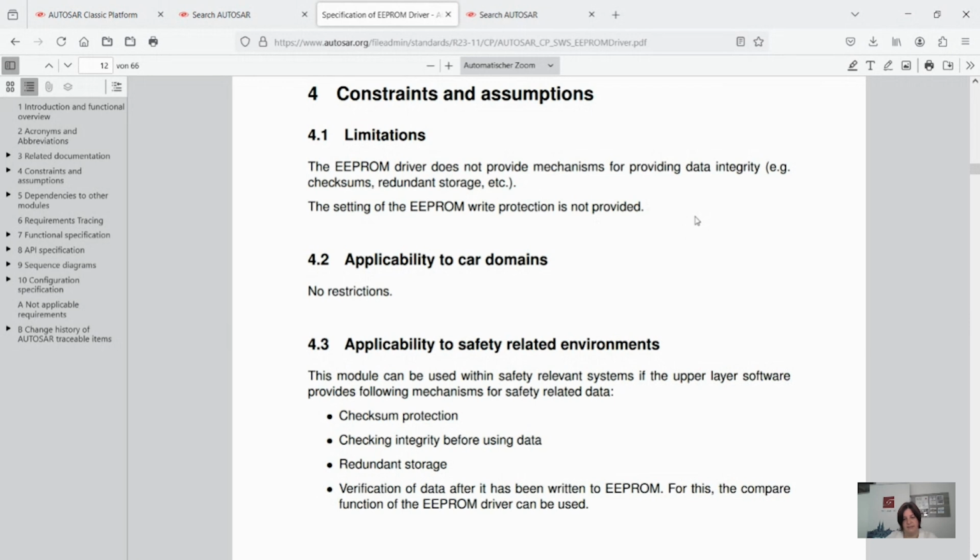All the details on the handling you can read, but there's one topic which is very, very important, which most likely you find in not so many specifications, and maybe only in the hardware specification of the EEPROM. Usually you cannot do an infinite number of write cycles, like deleting and flashing again, on an EEPROM, but it's limited. So you have hardware restrictions, and these are very, very important.